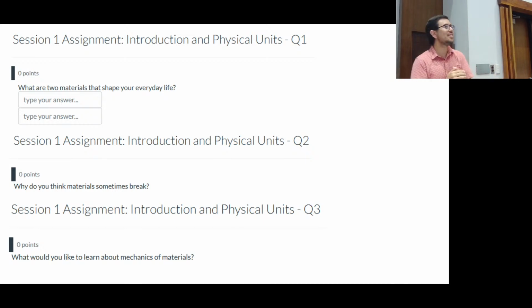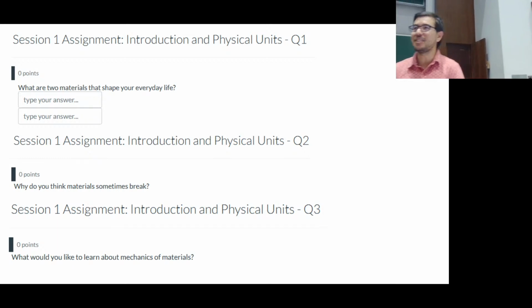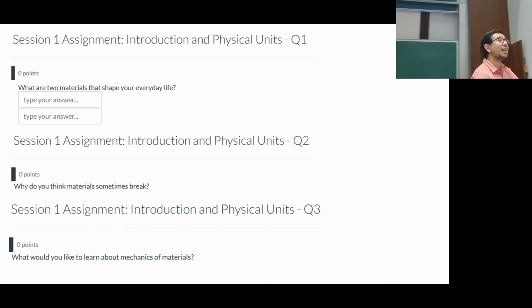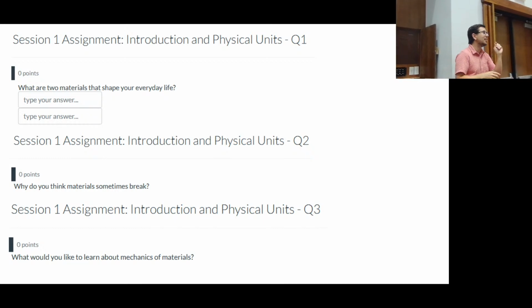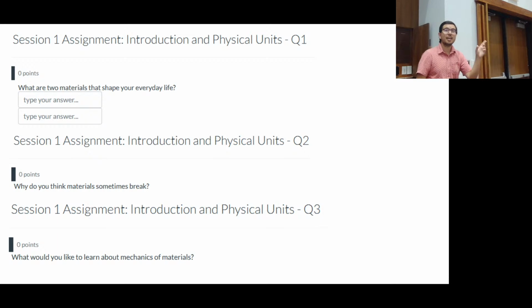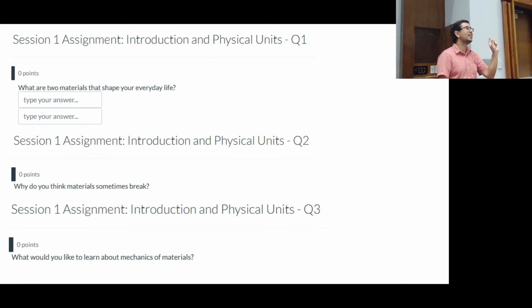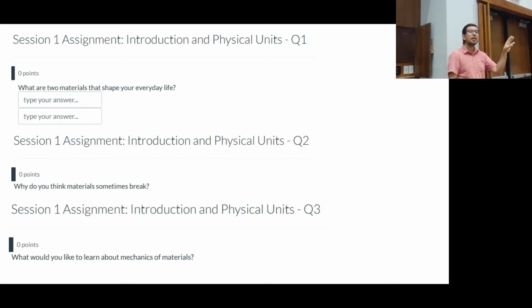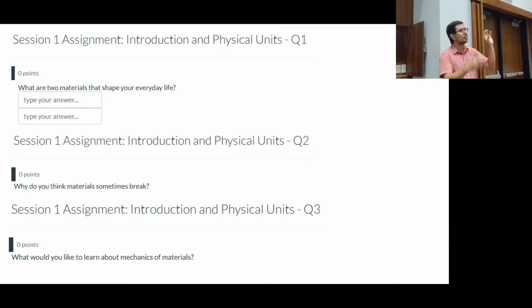You should come see me senior year. We do senior design projects on surfboard propulsion. Okay, good. But okay, so fiberglass. What is interesting about resin is that you can mold it, or you can use it to mold fibers onto any kind of shape to reinforce it and make it stronger. Okay. And it's one way, right? If you're using epoxy or polyurethane, you can't melt it again to get it to become nice and soft, right? It's a thermoset, so it's cross-linked.